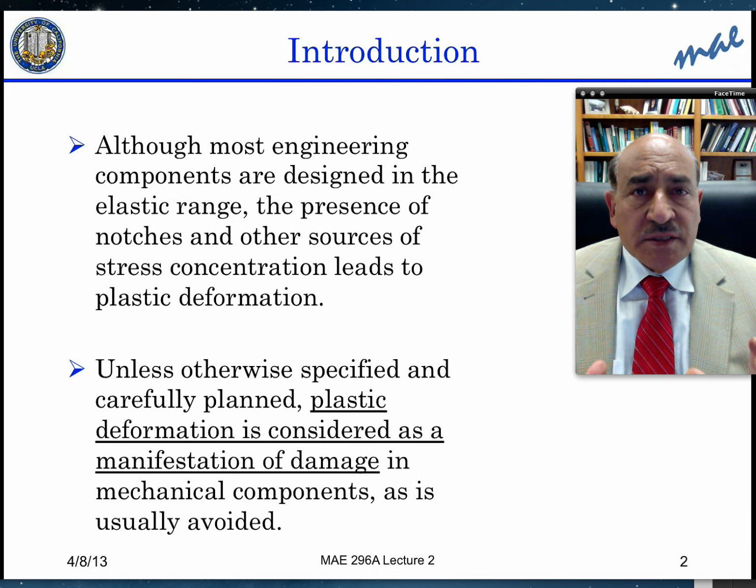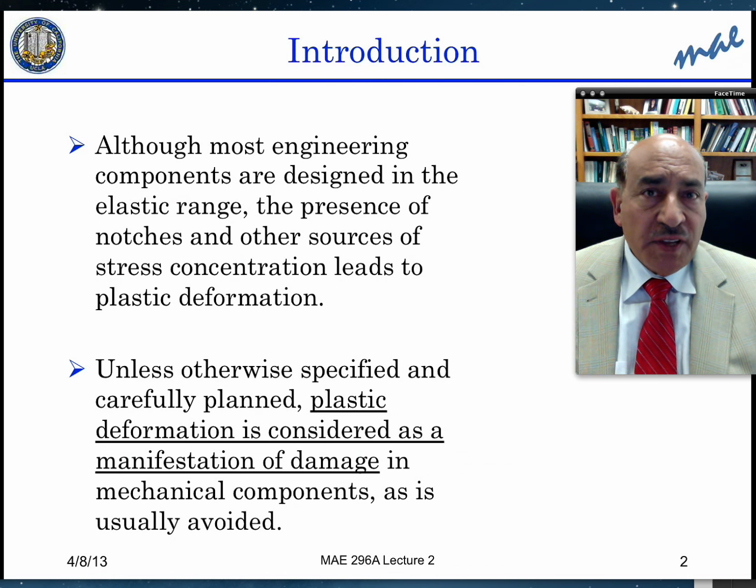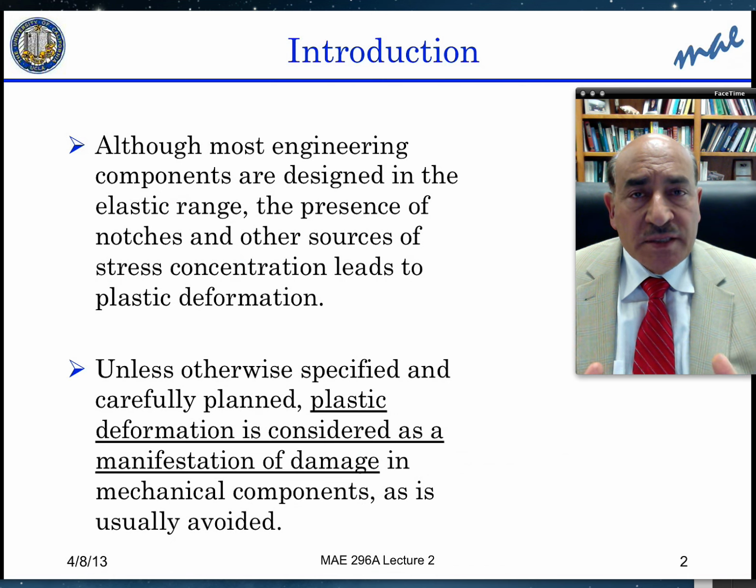Before we start, I wanted to point out that most failures occur as a result of excessive deformation. One way or the other, plasticity plays an important role. Unless it is otherwise specified and carefully considered and planned, as in your project, plastic deformation will be considered a manifestation of damage and failure. In some cases, around fillets and corners, you can allow plasticity to relieve the stress, which is part of the planning, but the designer has to be aware of such a situation.